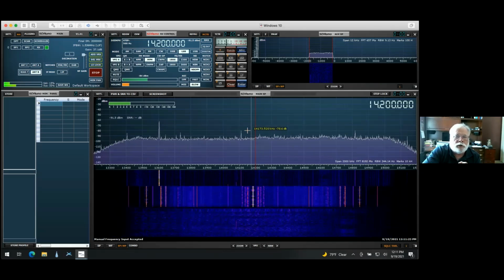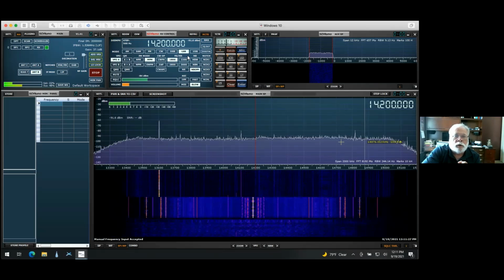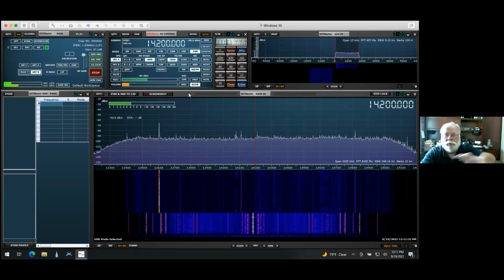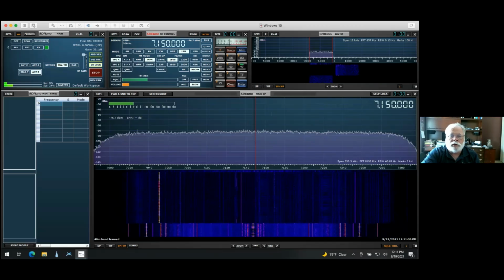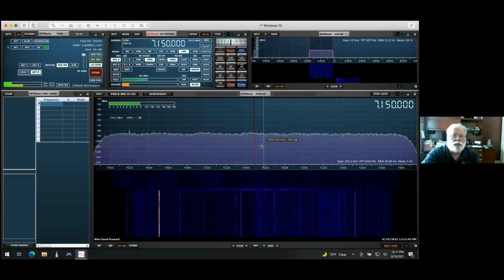I have a somewhat indeterminate spectrum window I'm looking at. I'm on LSB, whereas I should be on USB. So I have to make a lot of manual adjustments, whereas if I just clicked on the 40 button, it would have taken care of everything for me. The size would have been correct and so on and so forth. So that is a good way to get started.